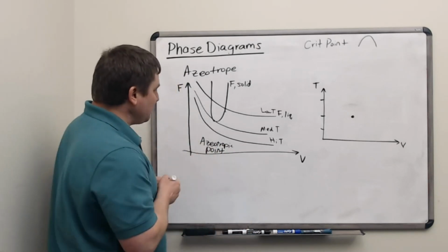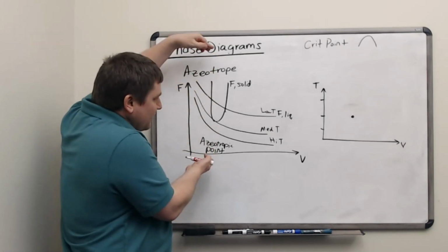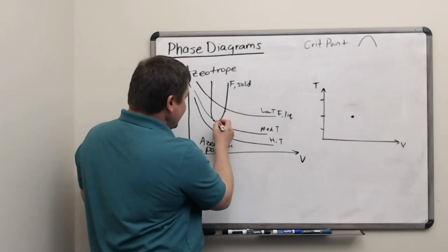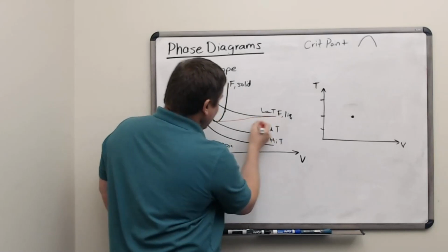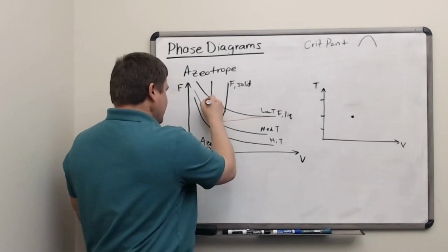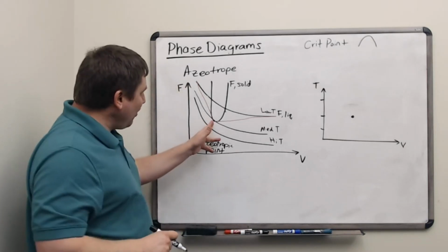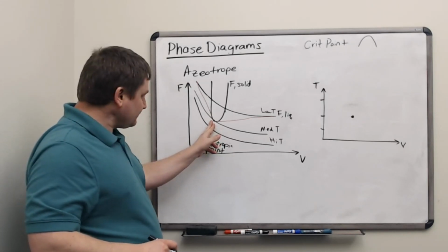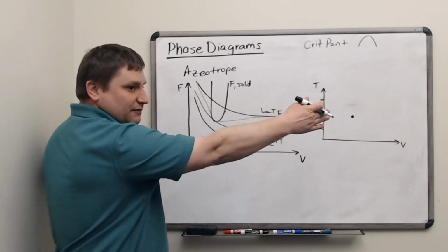If we look now at the low temperature, we'll see that what's happened is really in the azeotrope, one of these free energy curves kind of pierces through the other one as it moves. So at this other side here, we can form two convex hull lines, one, say, about there between the solid and the liquid on the right side, and a different one between the solid and the liquid on the left side. So we have a small window here where the solid can exist in a pure state, and then we have a large mixture region on each side and pure liquid beyond that.